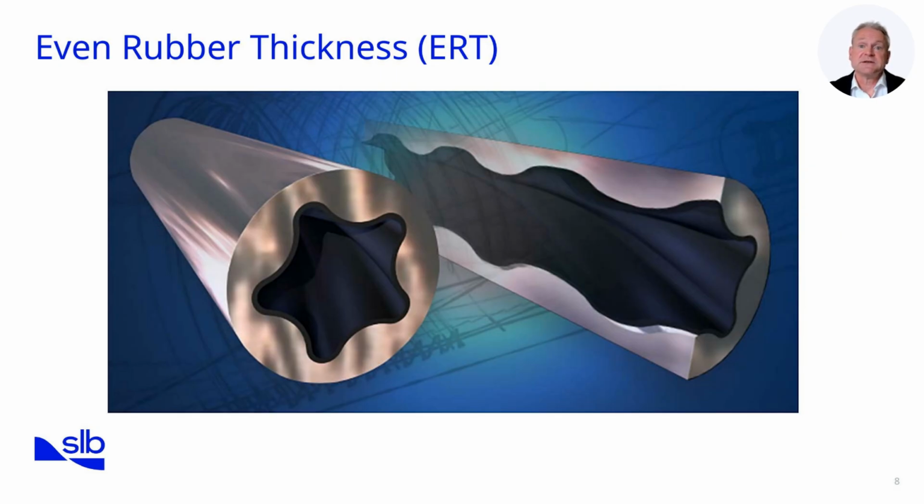Field studies have shown significant performance improvements in demanding wells, especially where downhole temperatures are high or mud systems are aggressive. While ERT stators may carry a higher initial cost, the reduction in failure risk and associated non-productive time often makes them more economical in the long run. For drilling engineers, the ERT option provides an attractive balance between performance, durability, and cost-effectiveness.